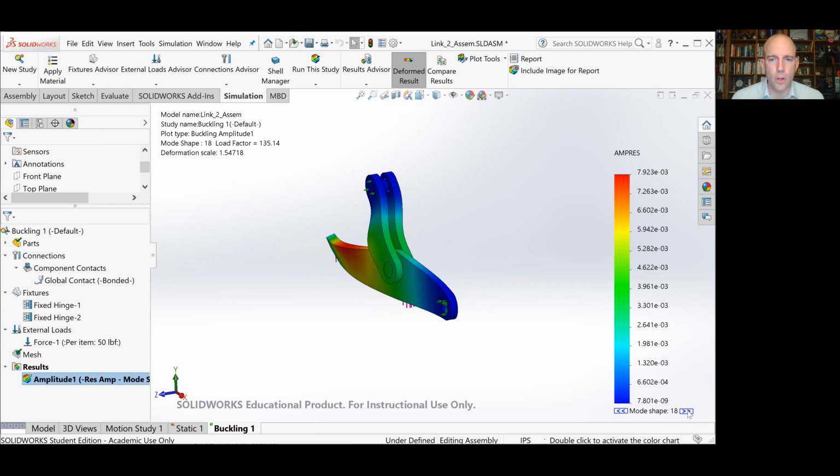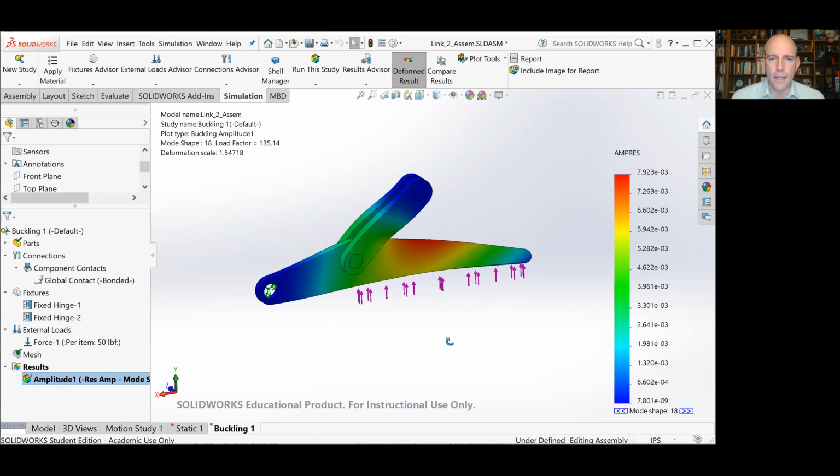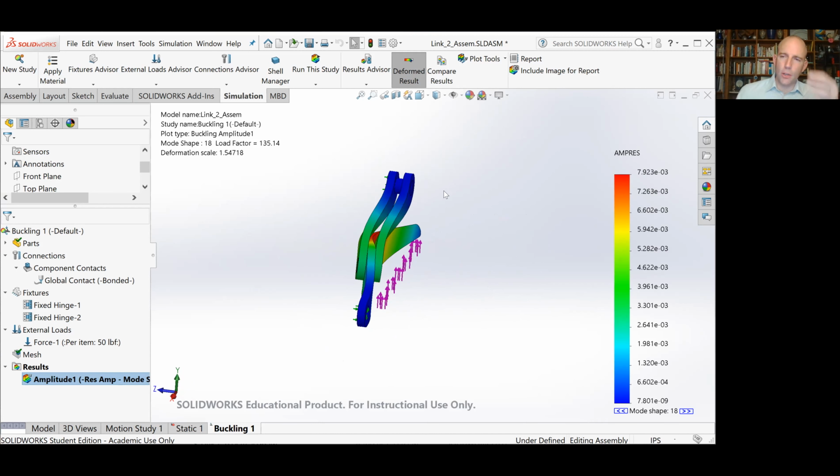All right, let's look at some of these nearby buckling modes. Oh, that's interesting. So here we have out of plane, but more like a 1.5 sinusoid for that second link. And we can see that in order for that to happen, both of the link 1 models in this part have to do a funny buckled shape where the tops are at the same angle, but they're offset, right? So that isn't quite captured by any of the simple models that we analyzed using our hand analysis.